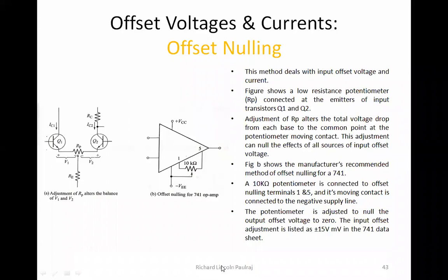Yes, sir. Okay, so ultimately, we are trying to have a system which helps us in nullifying the errors. We should not have any errors. We should make sure that both the transistors are either manufactured in the same way or the components used are made the same. When I say components made the same, it means same resistances, same input voltages. This can actually impact the way in which currents drop across the resistance.